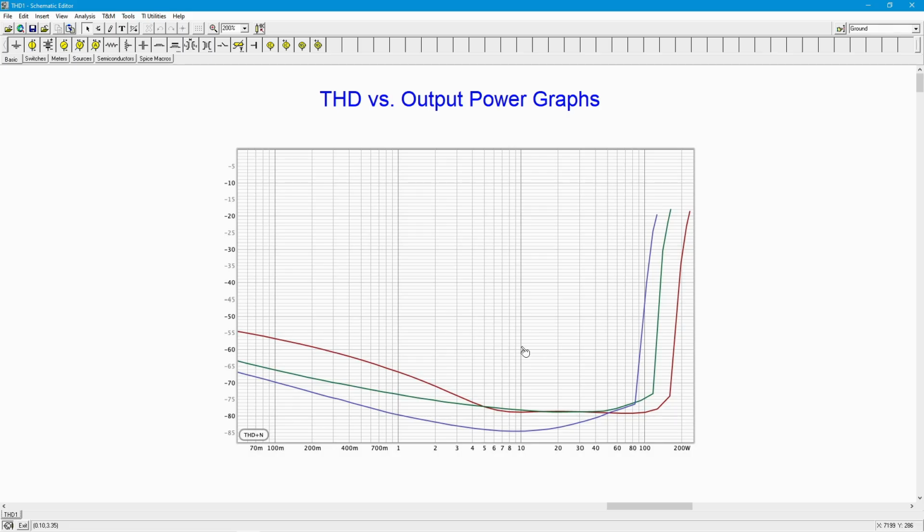Once you get a power amplifier that's below 0.1% across the board, in other words, from a low output to pre-clipping output across the frequency range, tested from 20 hertz on up, once you're down there, your problems are largely coming from somewhere else.